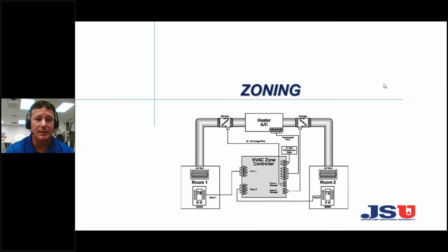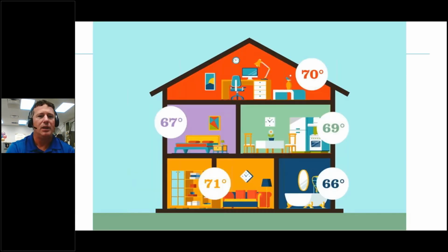The only thing we really had to contend with is what happened when you close off one zone and you increase the static pressure on your blower. So most of the time in the past, we worked with bypass dampers and barometric bypass dampering to help modulate and control how much static pressure we're putting on our blower when those zones are actually opening and closing.